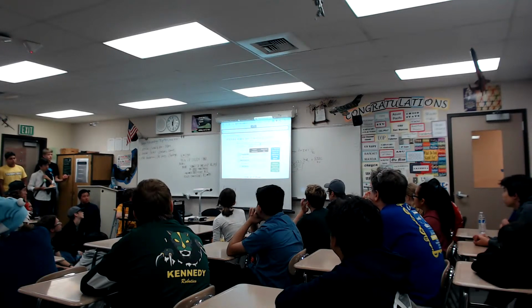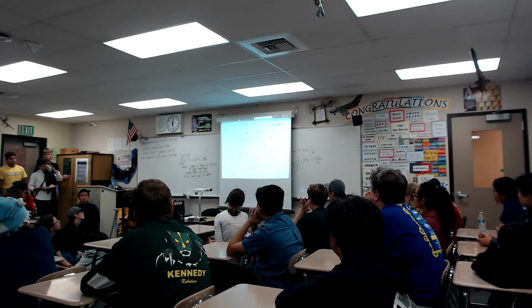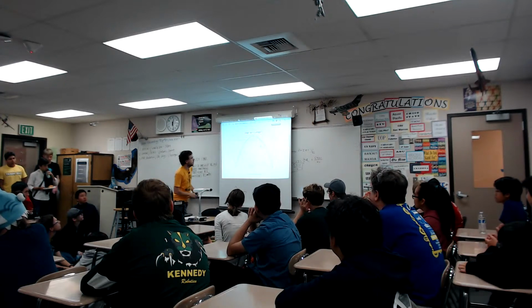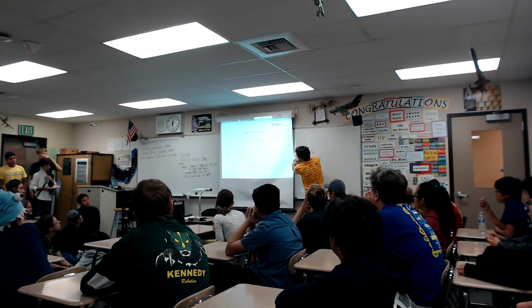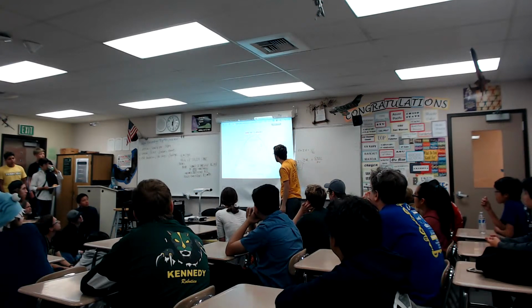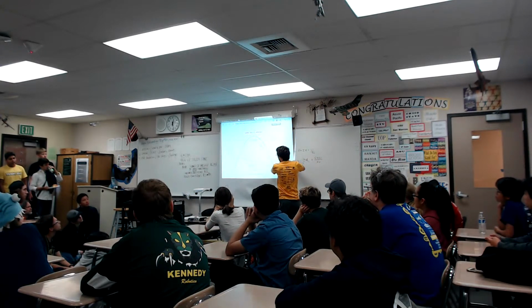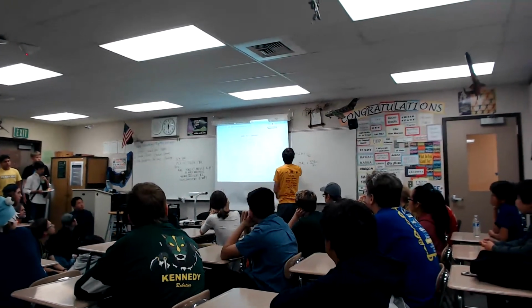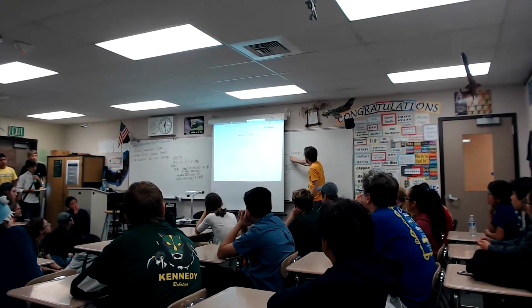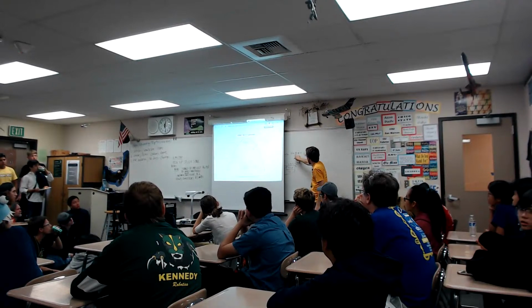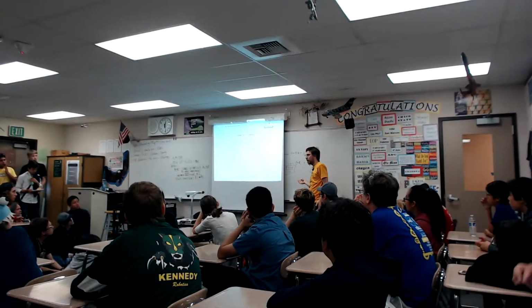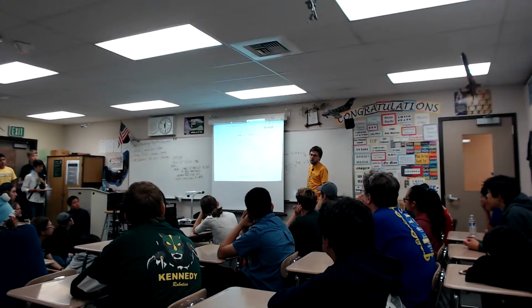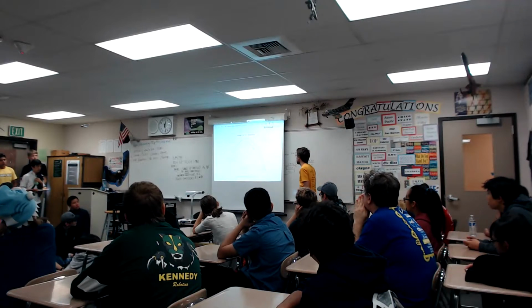So there's actually some more cool numbers we can go look at in here that someone's taken the time to put together. So this is actually a graphical representation of this equation here. We can see as the speed goes up, the current comes down, which is good. So with a fixed voltage, you can either have current or you can have speed. That's essentially saying as you're going faster, you get less torque, and you get more torque off the line, which is what we see in the robots, which is good.